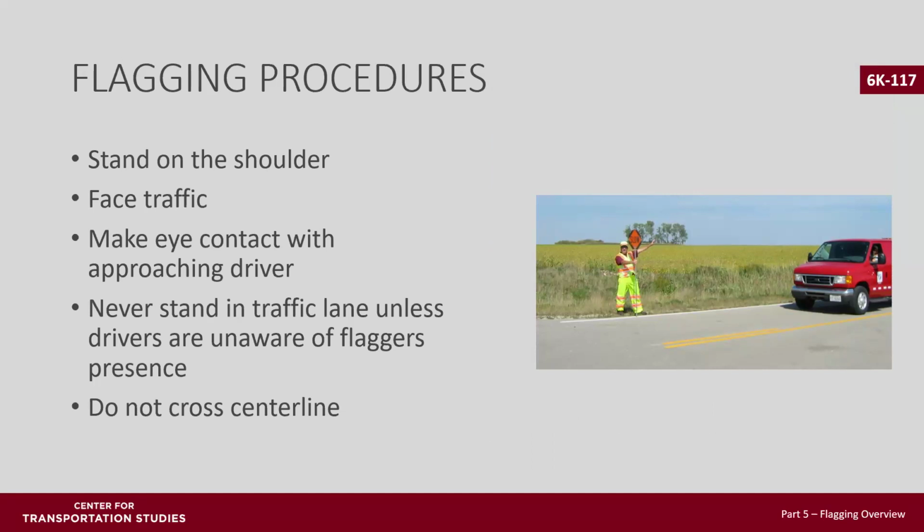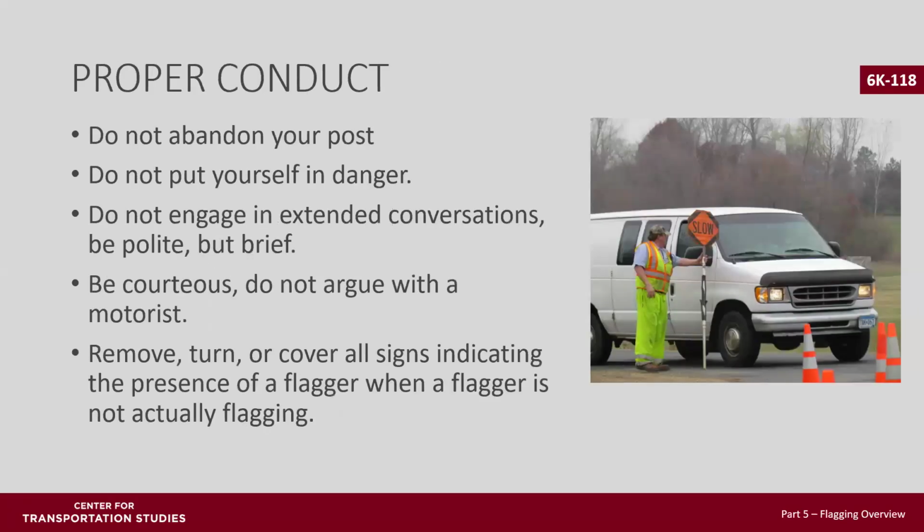As stated in the video for flagging procedures, stand on the shoulder, always face traffic. Make eye contact with the approaching driver. Never stand in a traffic lane unless drivers are aware of the flagger's presence. Do not cross the center line. You must earn the driver's respect. Do not abandon your post for any reason until the work is finished or a replacement flagger arrives. Do not put yourself in danger.